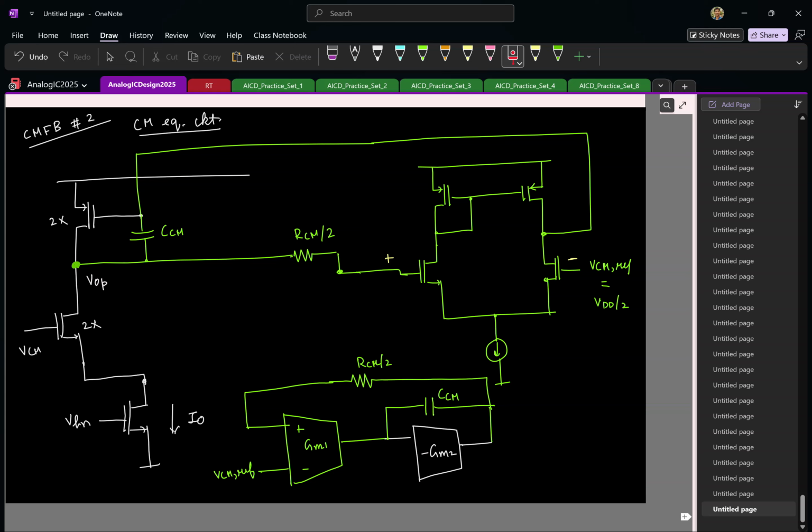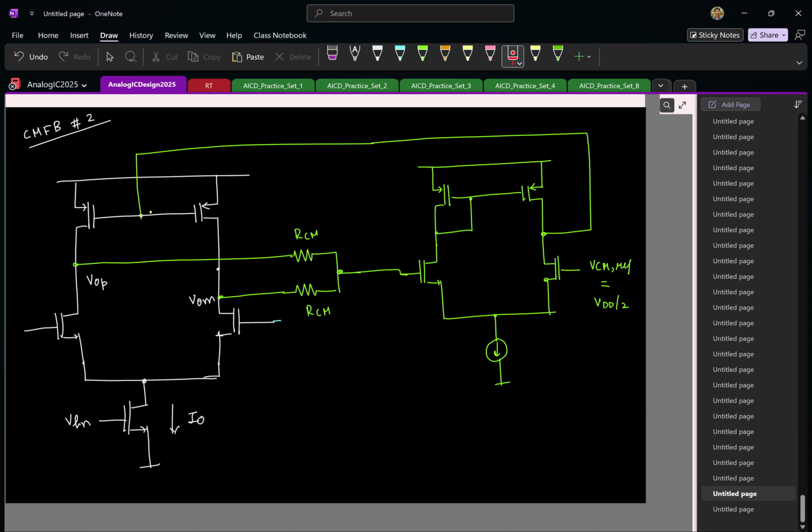So basically what that means is, if you don't do the compensation, anytime you have a common mode excitation or common mode jump, the common mode outputs will swing or ring large. But if you take the differential part, it will be fine. Just that the common mode part, or the actual individual outputs, will show a lot of ringing. But if you take the difference, you might be fine.